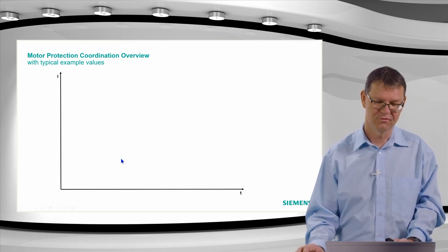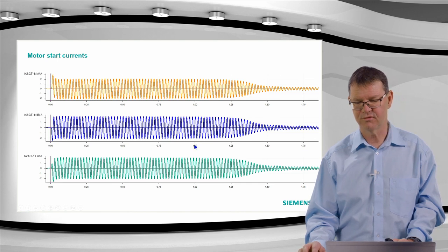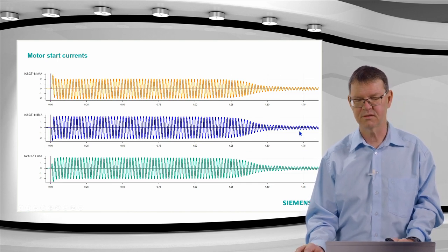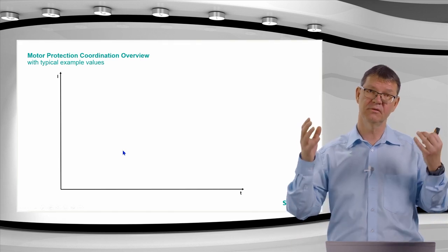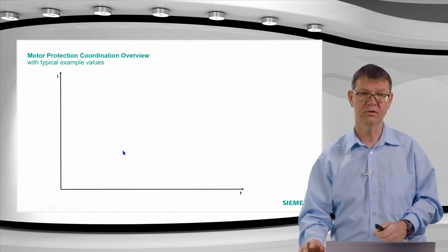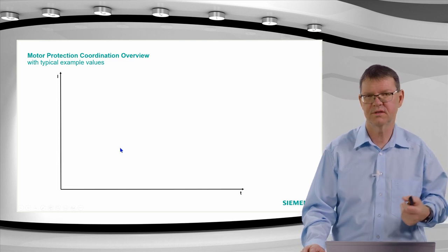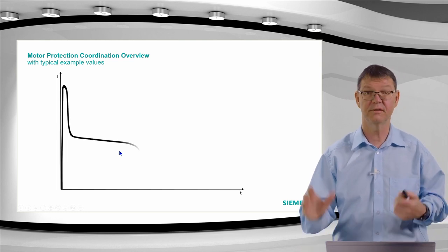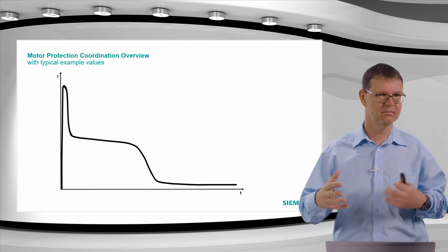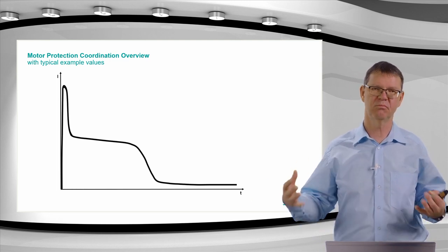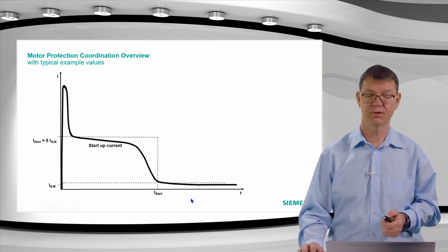And the length, as already, no, we did not discuss the length. So in the fault record here before, we see this is a very fast startup, only a couple of seconds here. If the load is heavier and maybe the voltage is not the nominal voltage, then the startup procedure can also take 20, 30, 40 seconds, maybe longer, even a minute, in that range. So a couple of seconds until roughly a minute, I think, will cover most of the situations for the length here for the startup procedure.